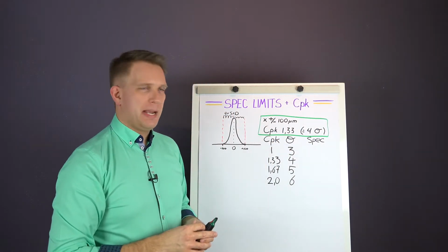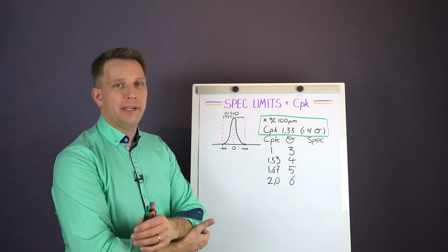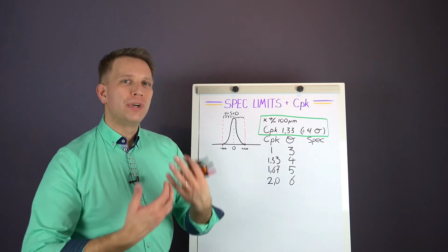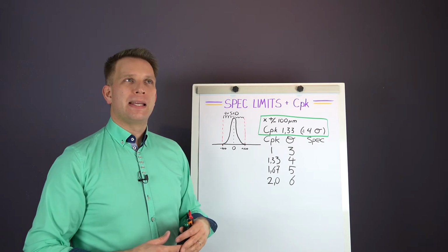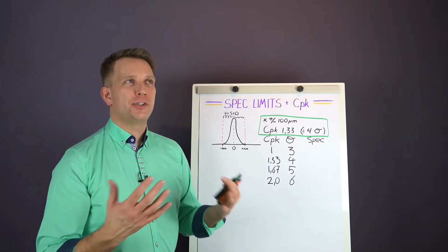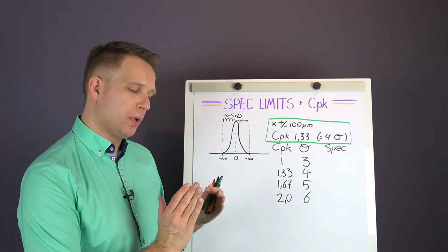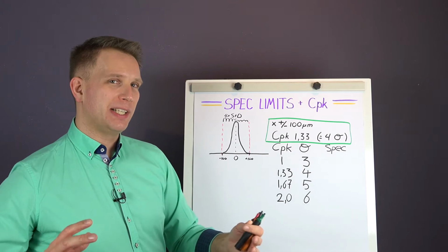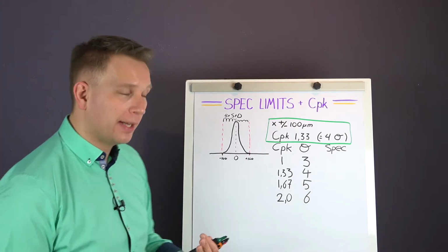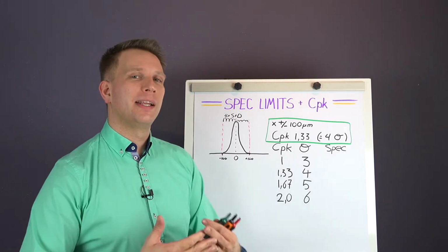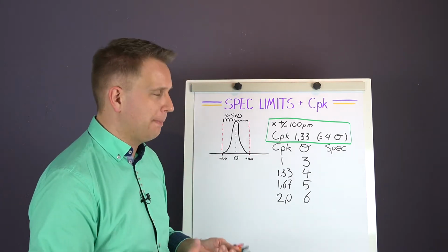So if we would make equivalent specs for that, if our customer really wants to have a CPK of 2, what should we give them as the tolerance that should fit with that? I'm a little bit at a loss of why specifically you would want to increase then suddenly the tolerance, because it sort of feels like cheating, although we will come back to it. There are some reasons why to do it, but first of all, let's talk about what it then means.